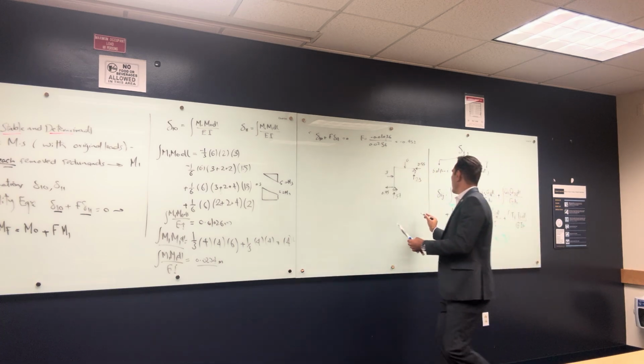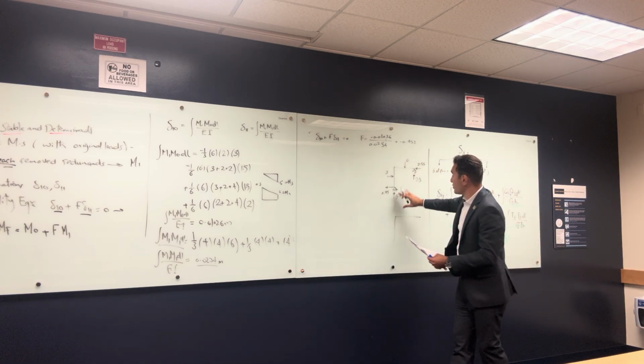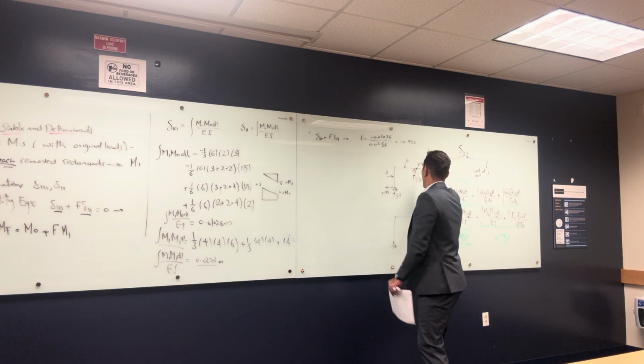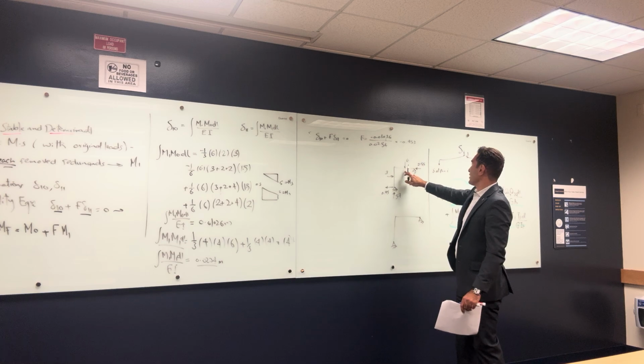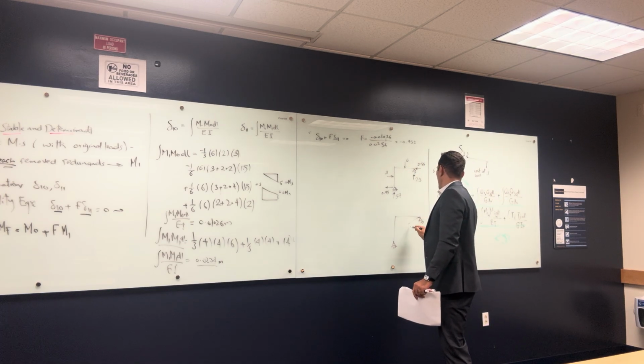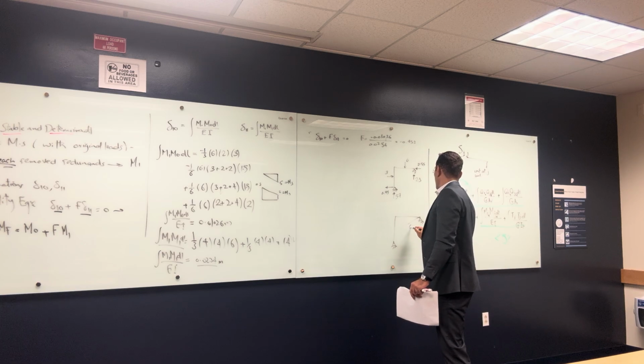So when you draw the bending moment diagram, you can use this reaction to draw it. Like get the moment here, and to get the moment here is going to be 2.3 multiplied by 3. So the moment here is going to be 6.9.